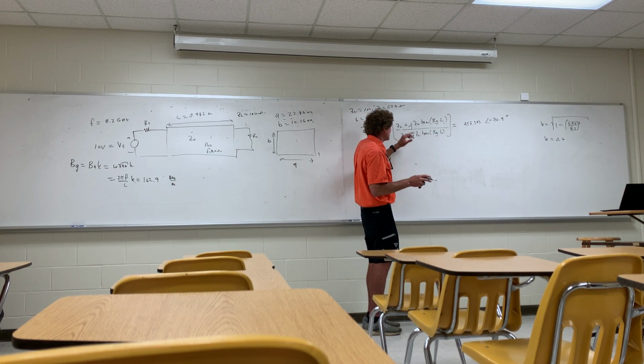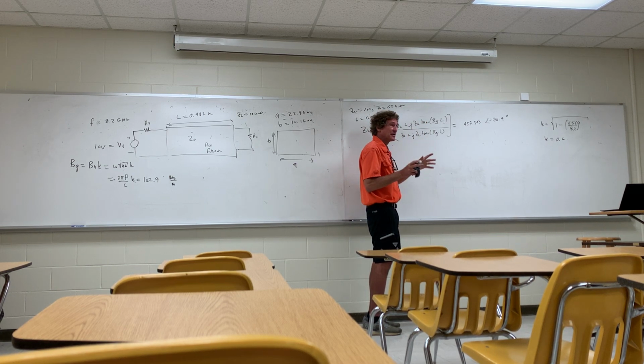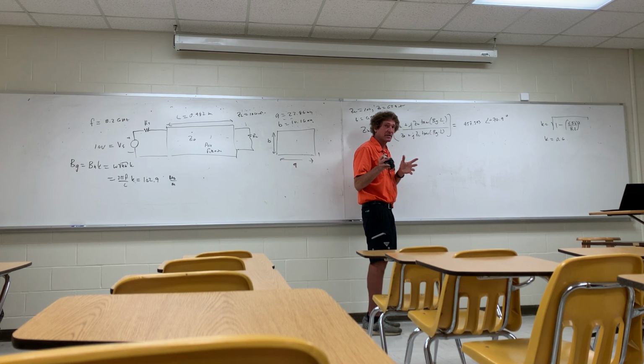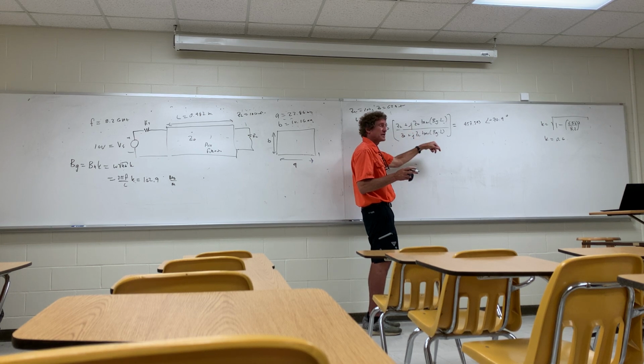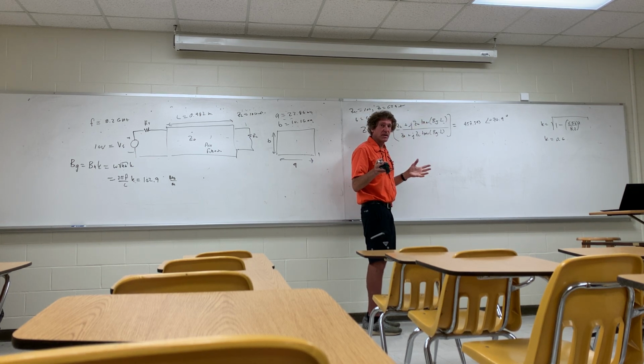And I'm just betting that's the problem. Now, sometimes when you take a real and imaginary number and divide by a real and imaginary number, your calculator gets a little confused, so you've got to take care about that. What I'd recommend is do this calculation first, store it. Do this calculation, store it, then do the division. I'm just telling you, these are the typical kind of problems you run into.